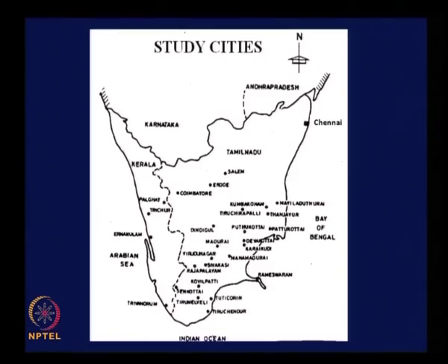Normally, under our condition, pertaining to these two states, September was found to have quite normal demand, not any peak demand condition. So data pertaining to the month of September was collected. In fact, monthly data was collected, even though weekly is sufficient. Data for 4 weeks were collected, and then the daily average was worked out, both in the case of bus as well as train, so that the data is more consistent and reflects the overall average travel pattern.